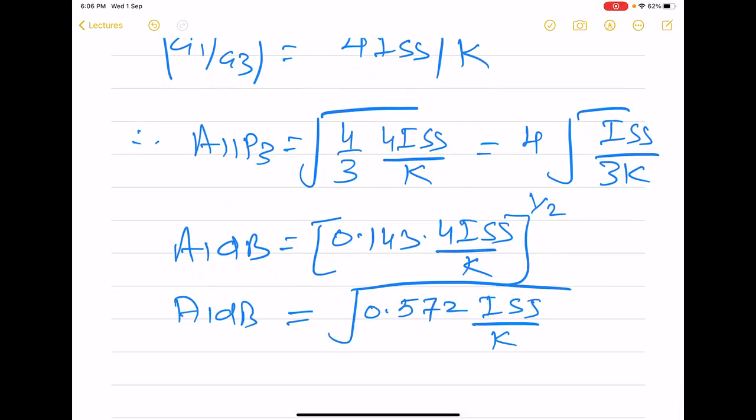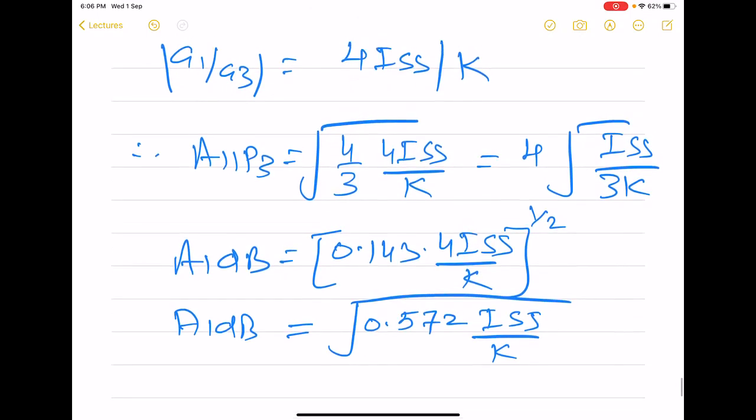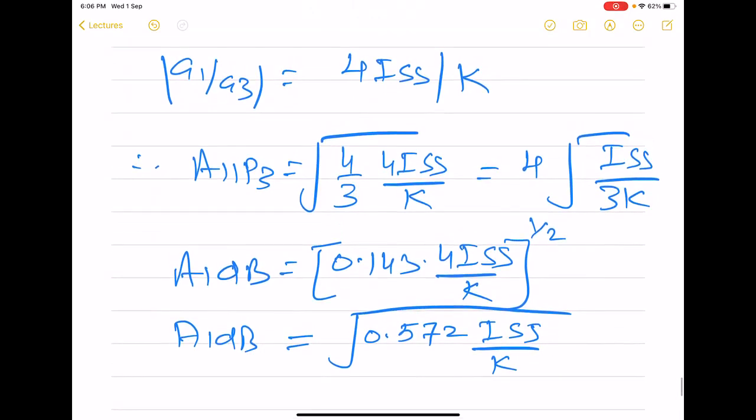So we see that whether the higher order nonlinearity appears in any amplifier is dependent upon the amplifier architecture. For example, for this differential version, whether we are going for the constant voltage version or the constant current version, and whether there is degeneration or no degeneration. And of course, all these are with respect to the simple expression for the drain current, which we use most of the time.